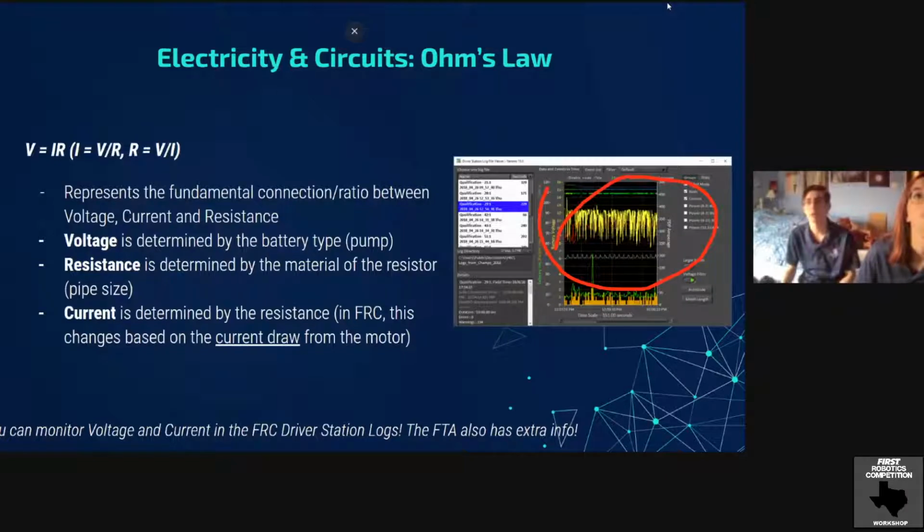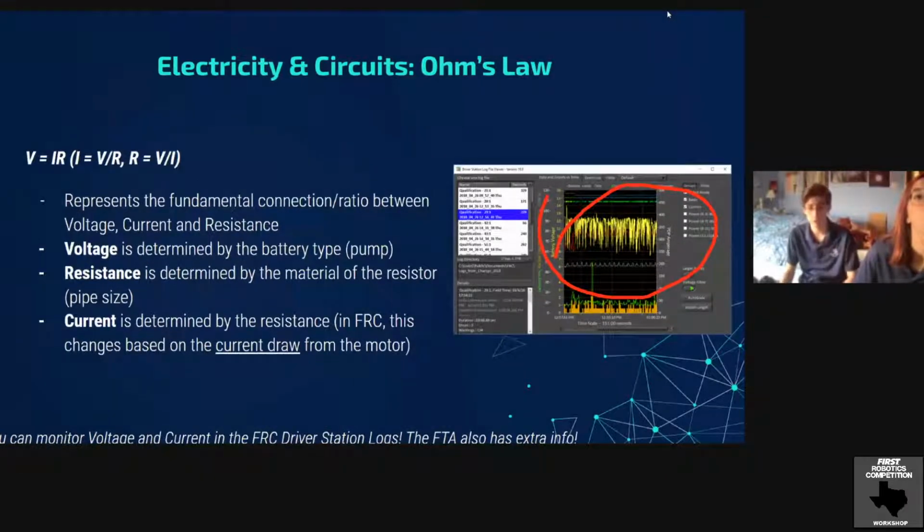And being able to calculate your motor's current draw is important to make sure, if you do your drivetrain gearing wrong, and a lot of people just slap together a drivetrain, but if you do your drivetrain gearing wrong, they will be able to push you across the field because not only mechanical advantage, but because you might brown out when you start to push against something.